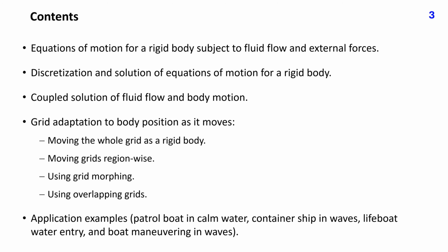This lecture deals with simulation of flows involving bodies whose motion is not prescribed but is driven or significantly affected by flow-induced forces. We first describe the equations of motion for a rigid body subjected to fluid flow and external forces. Next, discretization and solution methods for these equations are presented, followed by a description of the coupled solution method for flow and body motion.